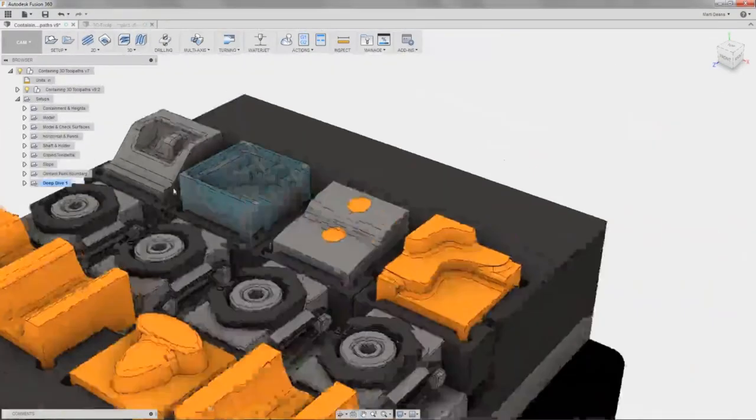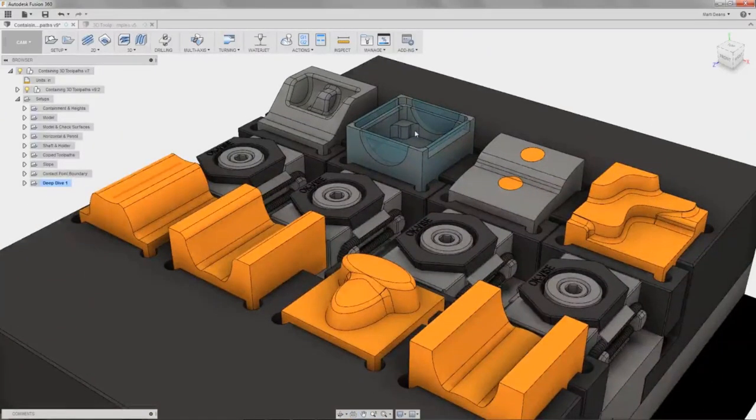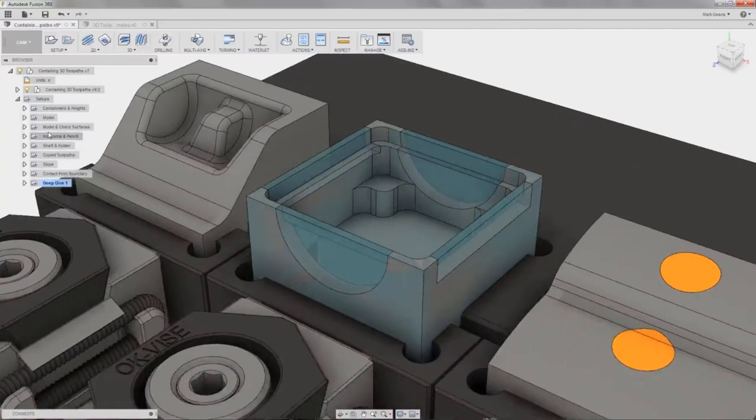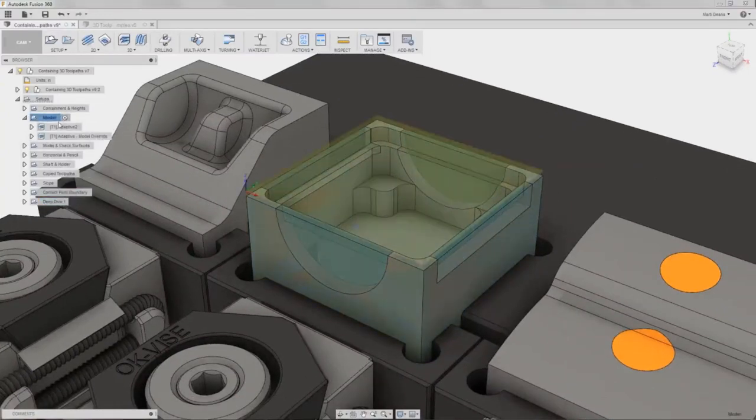Okay, so in this whole palette of parts, these three gray ones, I'm gonna use a lot of selections where I choose directly off the geometry and affect the toolpath that way. And all the orange parts are going to be ones where an intrinsic property of the geometry, like the slope or something else, is automatically going to determine how the toolpath is generated. So that's what the colors are. So in the next part, we're going to look at model, and I'm going to use this setup here.